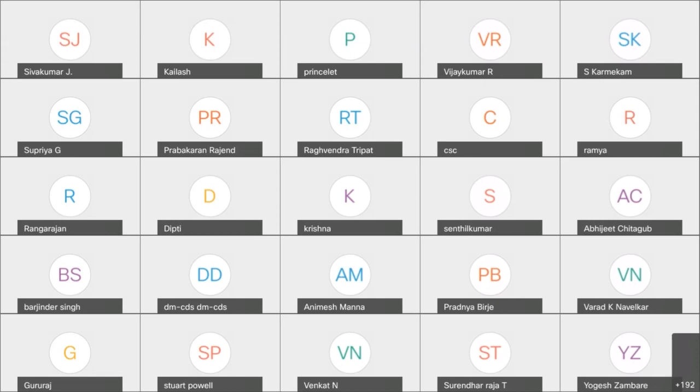From the standard's perspective, it may not be mandatory to be independent in the sense of something like TUV. However, the assessment has to be done independently. For example, the supplier developing a product, or the customer, can do the assessment. A different department or a different organization can perform it, and that also depends on the ISO 26262 confirmation measures. There is a detailed table showing which important work products undergo which independence level with respect to the ASIL level. That needs to be followed.